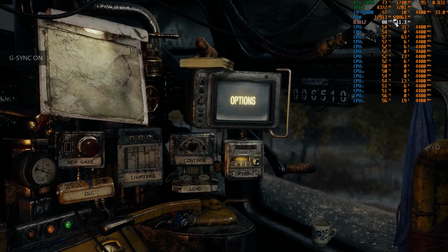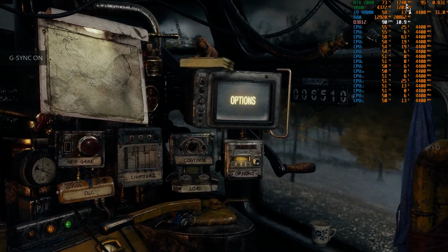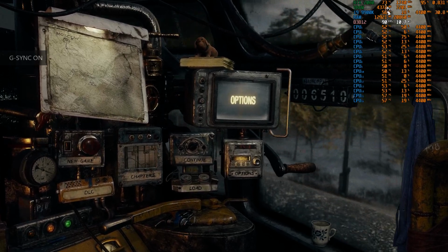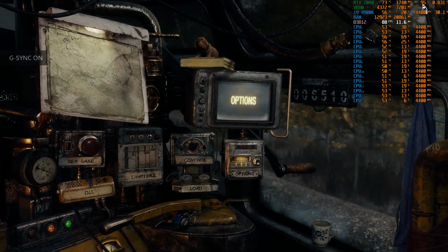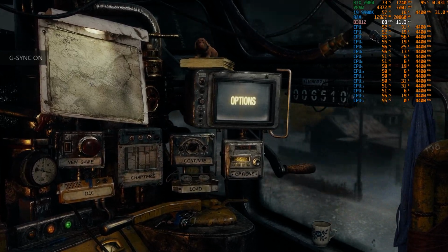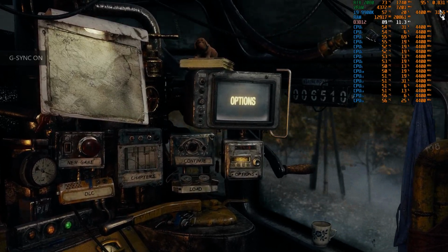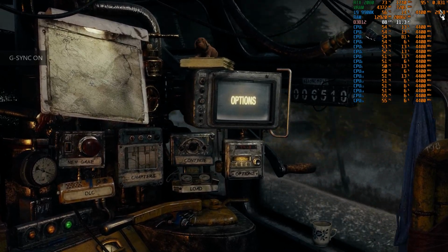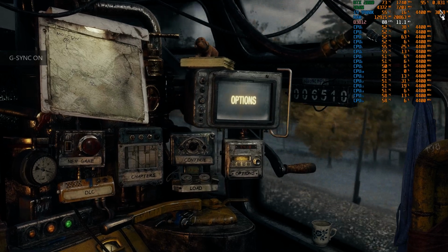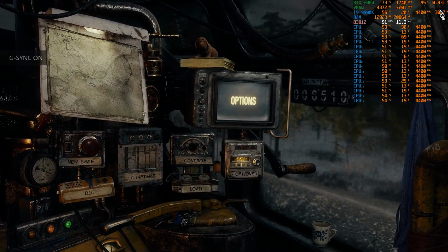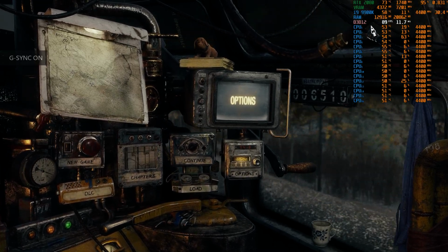So we increased by 30 megahertz and we gained 1 degree Celsius because of the 0.80, because of the increasing voltage. But basically this is the concept of how you overclock and undervolt at the same time, right? I'm happy with this profile.